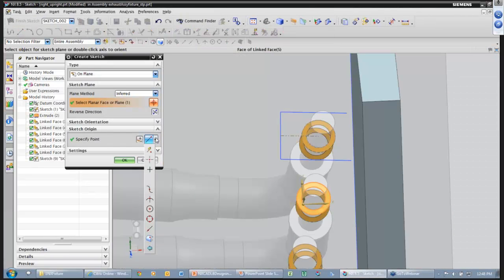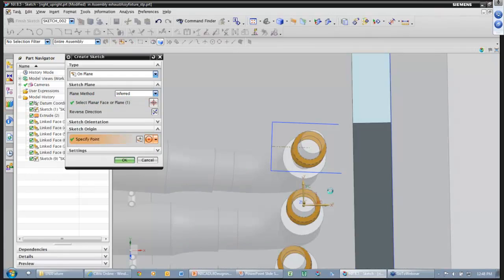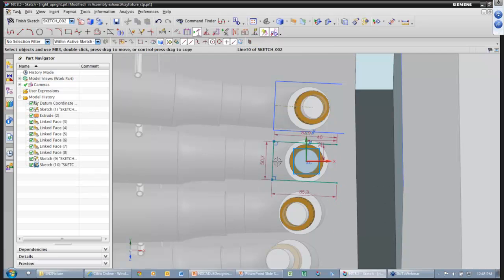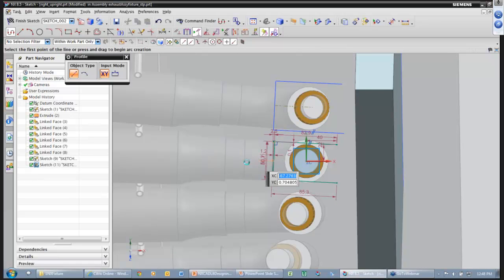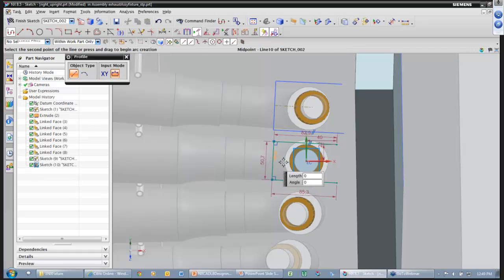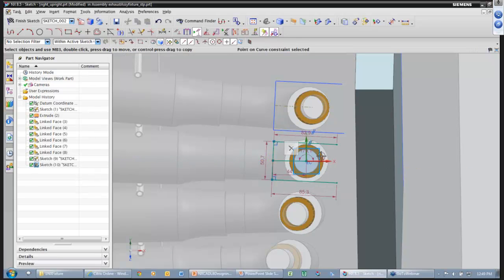I'm going to create the sketch again. Put that on center. I'm going to draw the profile off. I'm going to infer some constraints. There's parallel, so that'll give me the same orientation. I'm going to build another center line here. Go from the midpoint here over to the center. I'll make that construction again.